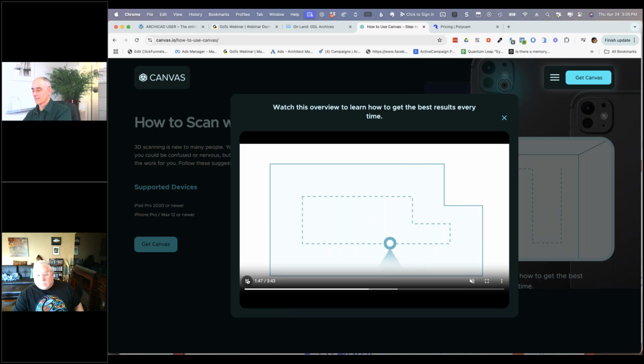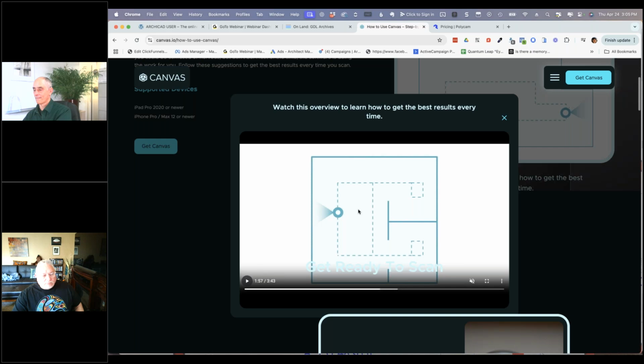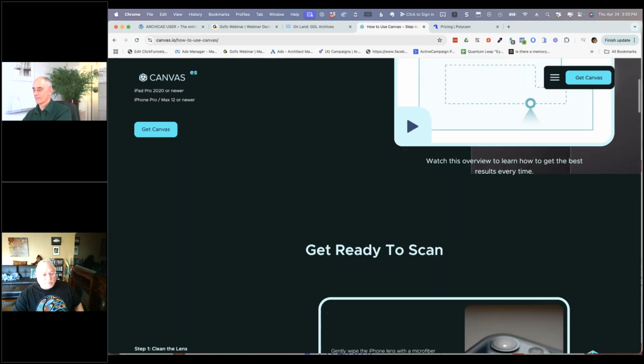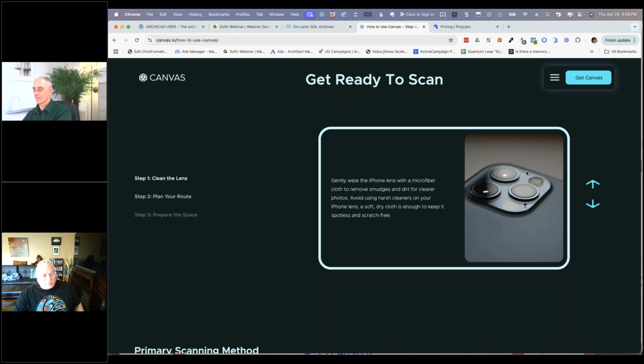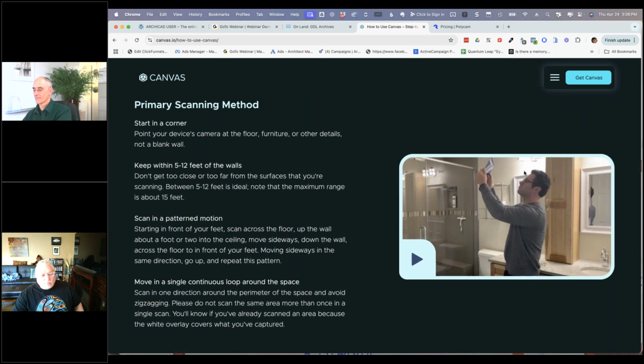The other thing, honestly, the best time to scan an exterior is on a gray overcast day. If it's bright and sunny, it can be really difficult, and when you're scanning back towards the sun. The other thing is it's not like using Matterport where you can scan for thousands of feet away. Ideally, and it'll say when you're scanning, hey, you're too close or too far. Its ideal range is like 7 to 10 feet.